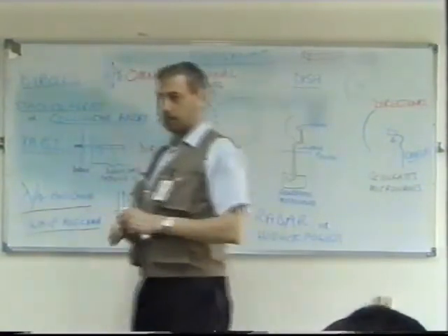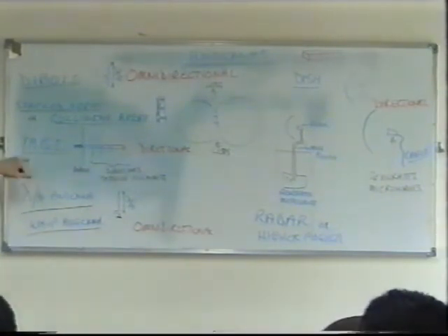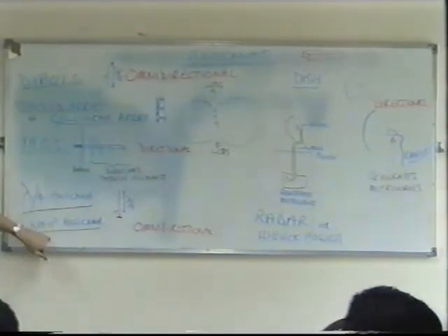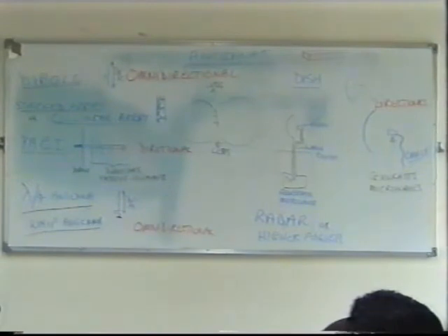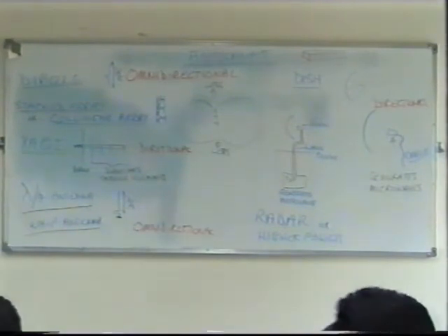Basically, we've got two uses of radio, either point-to-point or mobile. This is the sort of antenna we would use for mobile. The quarter antenna is a whip antenna. It's an example of a quarter antenna. Sometimes they call it a whip antenna, yes. You might hear this word used. They mean a quarter wavelength.